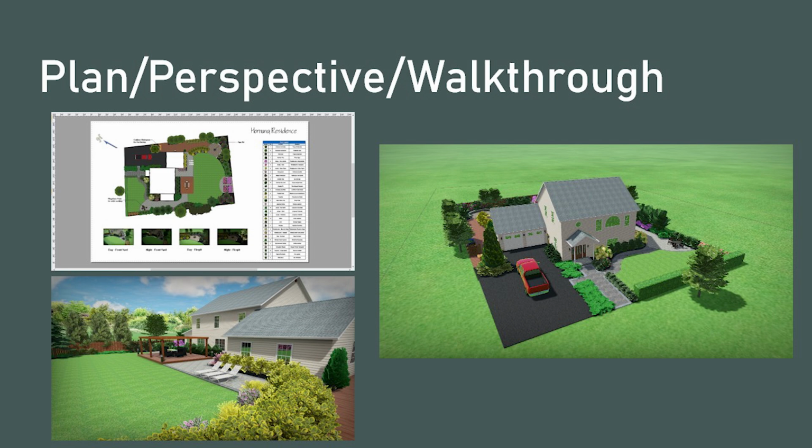For this project, we imported the background image using the Import Wizard tool. We then scaled the image with the Scale tool, which is very similar to both programs used before. This let us confirm the image was set to a 1:1 scale. This step is crucial to the making of this project as it lets us create our projects in real-world dimensions.